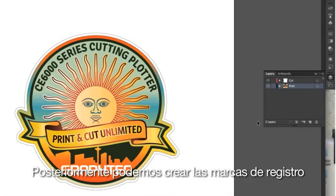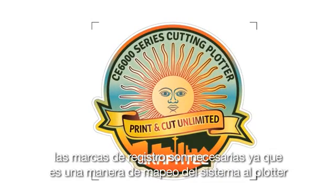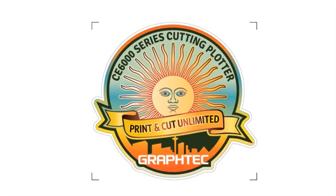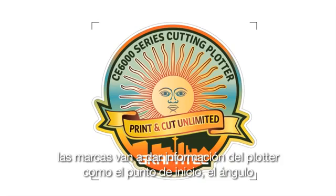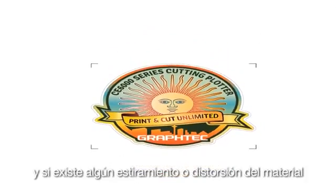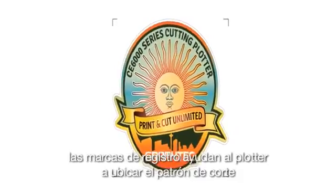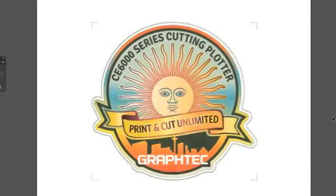Next, we can create the registration marks. Registration marks are needed because they are like a mapping system to the cutter. Once they are scanned by the registration mark scanner, the marks provide information to the cutter such as the starting point, the angle, and if there is any stretch or distortion.